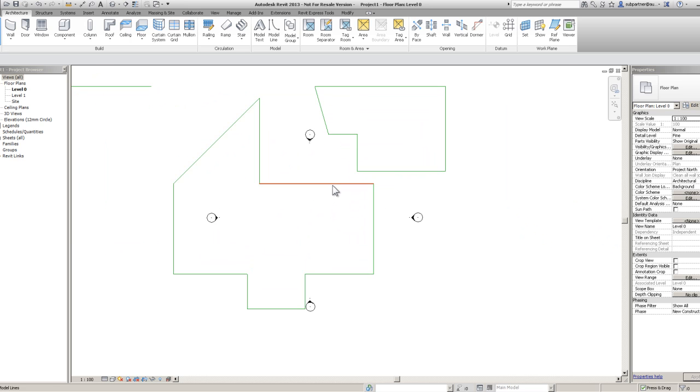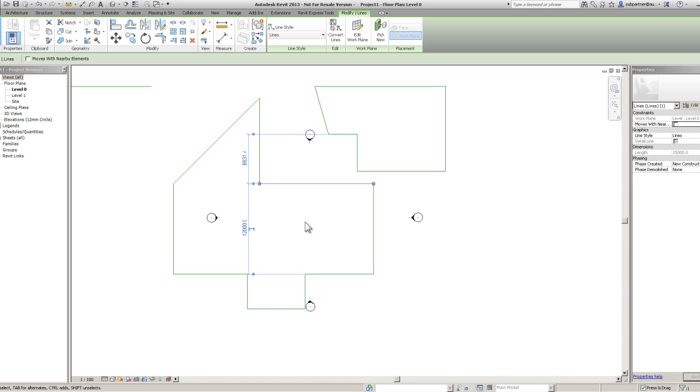Now, when it does that, that's what we call a soft select. You see I move my mouse away, it goes, move it back over it, it comes back, okay. Now basically what soft select means is if something is soft selected, left clicking on my mouse will select that object. I know that sounds pretty obvious, just bear with me for why I'm telling you that. So if I hover over that line and left click, you see it's picking that line. Again, we have these little dimensions turn up. We're going to come back to those in a little while, so please just ignore them for now.